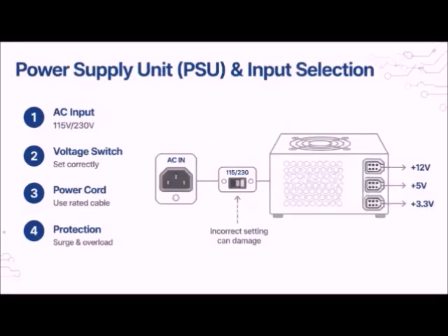3.5 power supplies, PSU. Power supplies convert high-voltage AC input from utility lines into stable, low-voltage DC current. Input selection. Manual dual-voltage switches toggle between 115V, standard in North America, and 230V, standard in Europe. High-end power supplies use auto-switching circuitry.